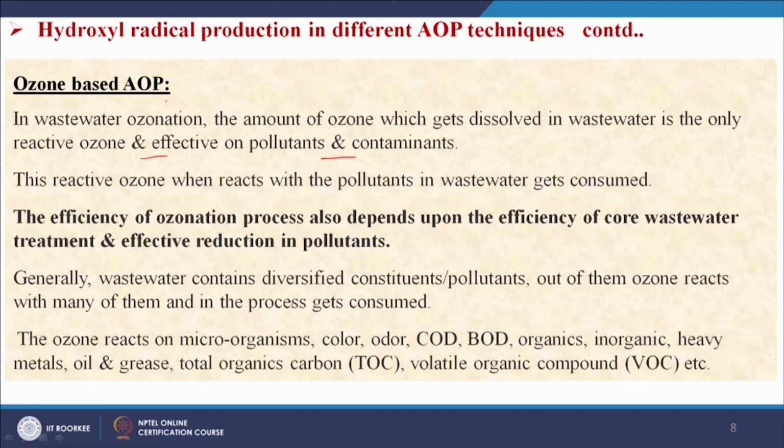Generally wastewater contains diversified constituents and pollutants, and ozone reacts with many of them and in the process gets consumed. Ozone reacts on microorganisms, color, odor, COD, BOD, organics, inorganics, heavy metals, oil and grease, total organic carbon, volatile organic compounds etc.